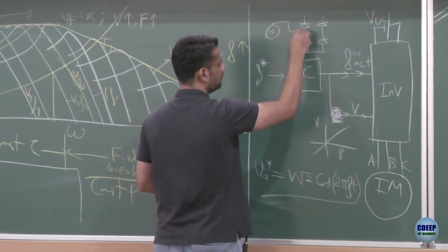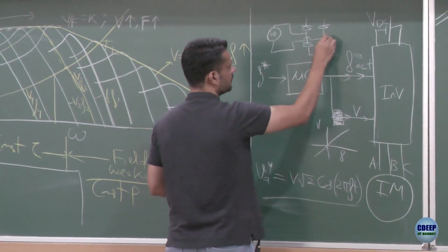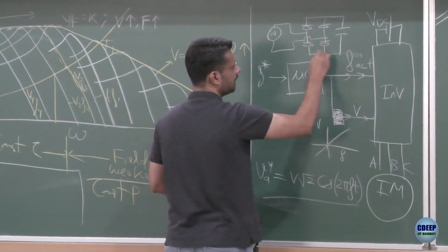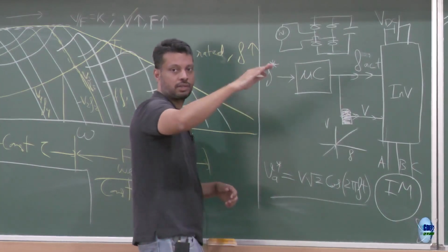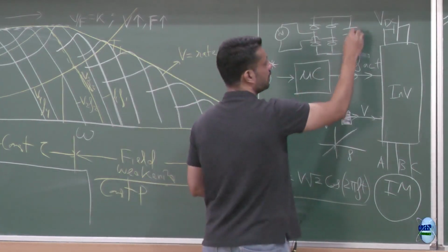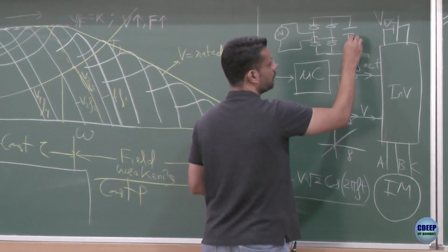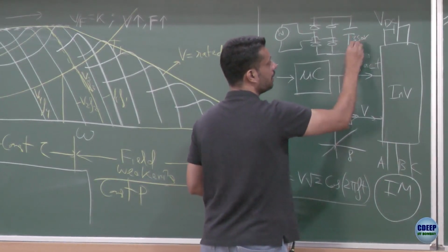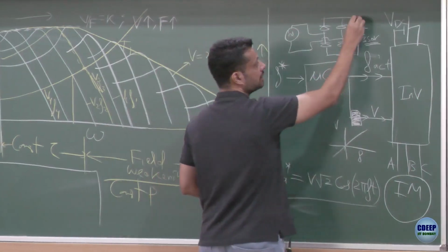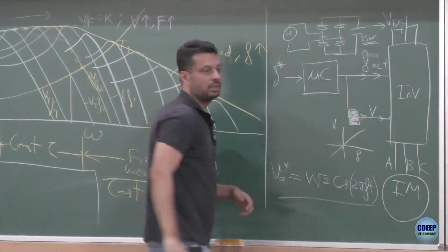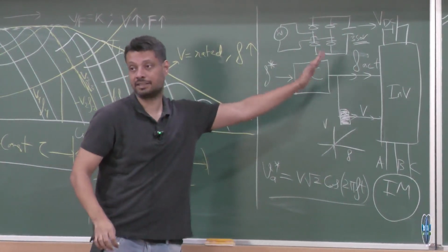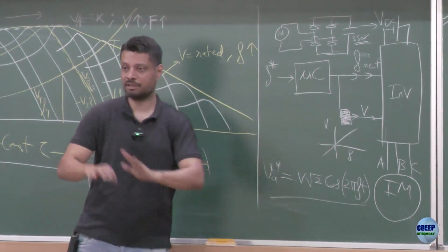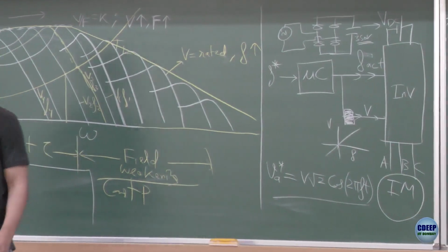So this DC was actually getting produced by a single phase AC going to most likely a full bridge rectifier, and then you have a capacitor to make sure that ripples are not there. There's almost a smooth DC, and once you have this smooth DC of approximately 350 volts, which is the peak value of the AC voltage, this is something which you supply to the inverter, right? So this box had everything. This box had the rectifier, this capacitor, this inverter, a controller, everything was there in this small form factor.